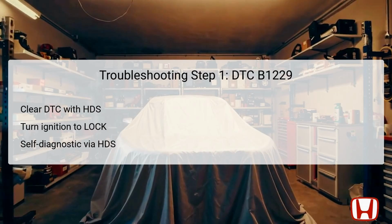The first step in troubleshooting DTC B1229 involves verifying the problem using the Honda Diagnostic System, HDS. Start by clearing the existing DTC to reset the system. Once cleared, switch the ignition to the lock position and then turn it back to the on position. This action prepares the vehicle for a self-diagnostic check via the HDS or the climate control unit.